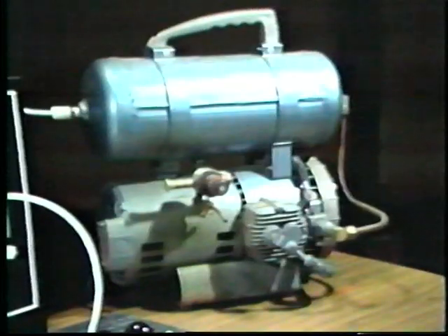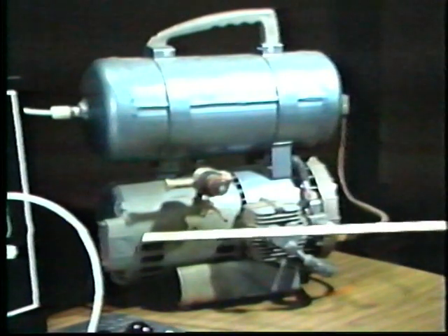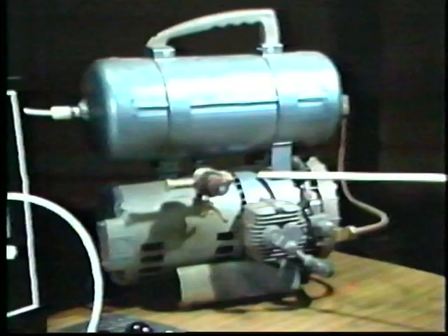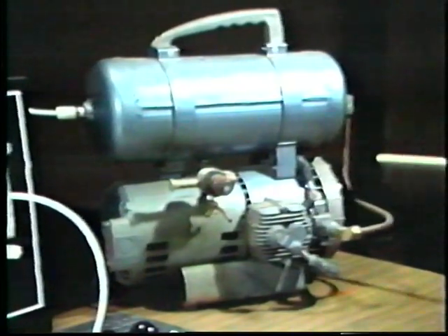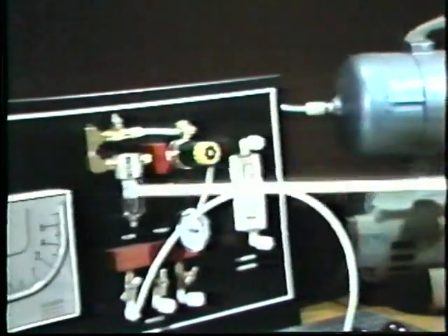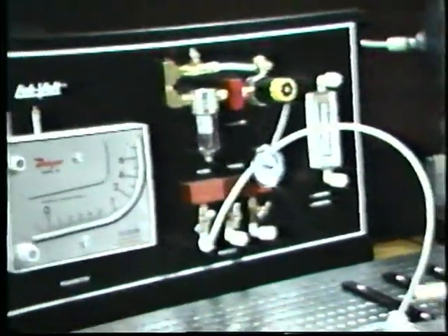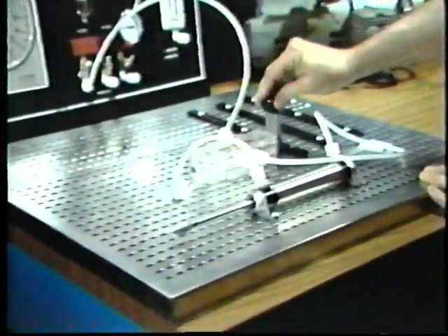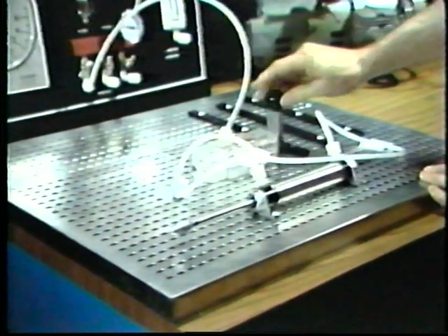Okay, what is a pneumatic system? Quite simply, it is a system that can store and transmit energy in the form of compressed air. Another form of energy, usually electrical energy, is used to drive some kind of compressor. Then the air, under pressure, is controlled and directed by the system, and the energy which has been stored in it by the compressor is delivered to the place where it is needed to perform work.